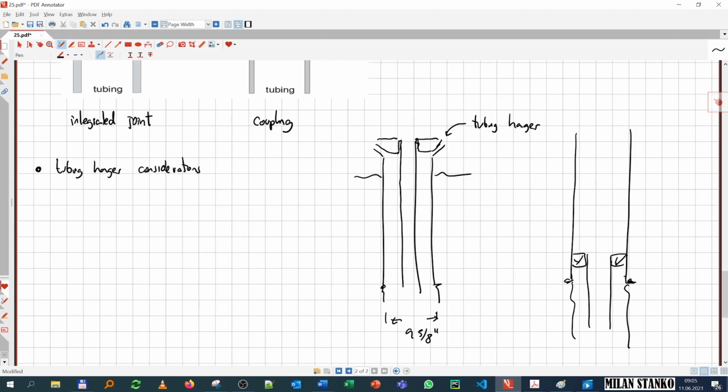But something more important is that typically you don't have only the tubing. For example, you have a pressure gauge, which is here, at the downhole. This is a downhole pressure gauge. Then you have to send the signal, so you have to make a hole through this tubing hanger, and then you have to pass the line. In this case an electric signal, you have to pass it through some cable. And to avoid damage, typically you have some sort of a clamp.